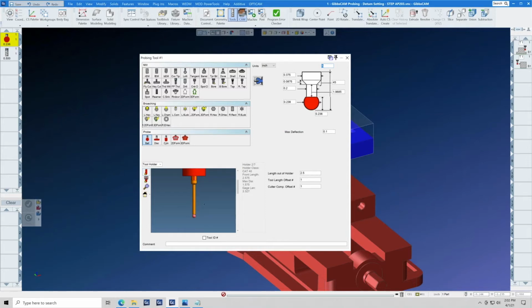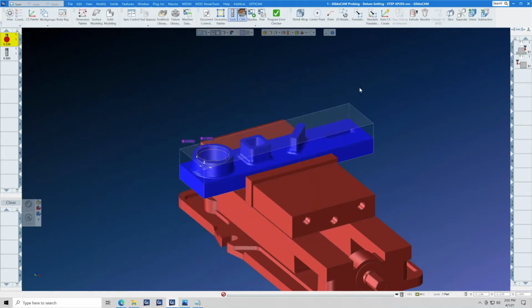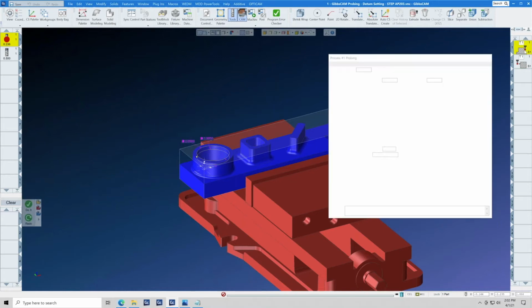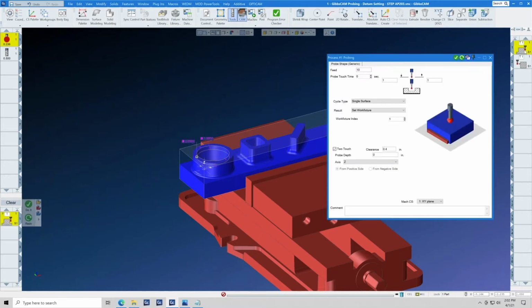The stylus that we currently have here is the standard 6mm by 50mm stylus that comes shipped on 99% of machine tools in the United States. And the first task that we have in front of us is, yes, we are going to use the probe as an edge finder. But before we start doing some clicks, let's explore why we would want to create our probing data and integrate it in the program rather than to have someone manually probe this.